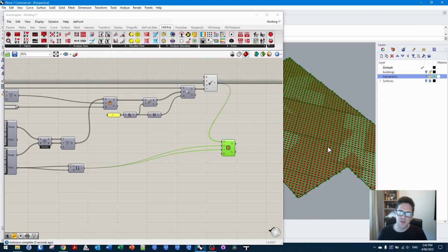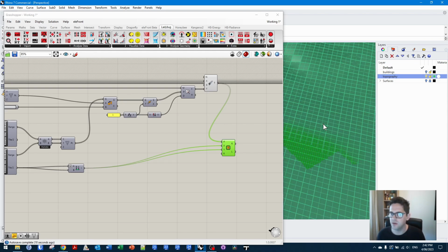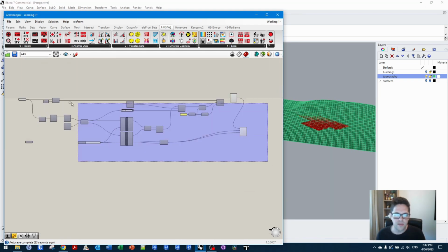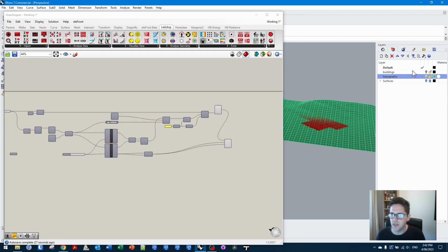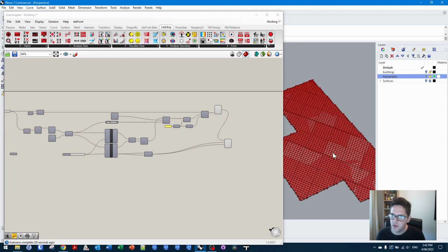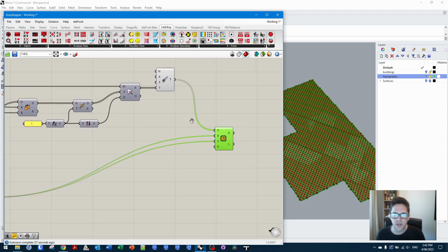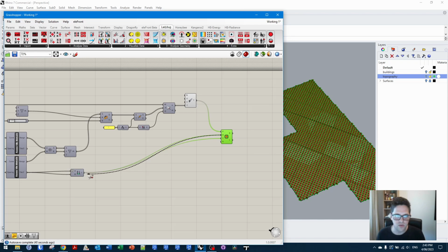The good thing about this method is, because we're re-intersecting it with the original surface, we can technically make this work for undulating surfaces as well. So we can actually take these points and now generate them based on the terrain of the test. What I can do is just turn my topo back on, and I can get my test points and point them back the other way. Now what I might do for now is let this become a cluster that just deals with the surface itself, and then we'll do an additional mesh ray test to push these at the topo itself, just to avoid overcomplicating the process. So we don't actually need these to be rectangles yet. It's too early. We just need points.